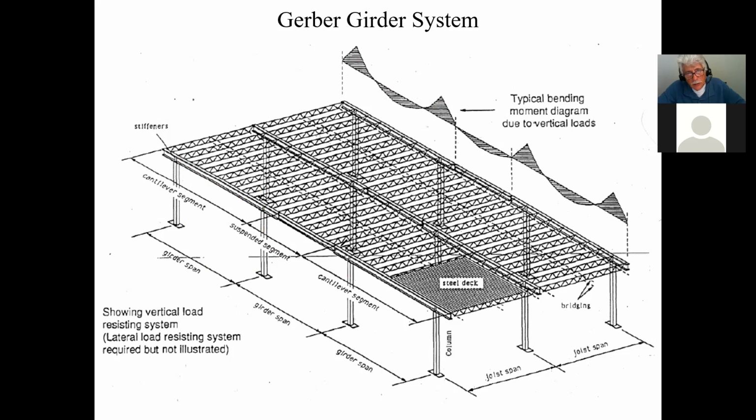Now you see here, this is the beam that gets suspended. Even for this beam here, instead of it spanning from there to there, the span would only be from there to there, and therefore even this would end up being a smaller beam. So these drop-in or link beams end up being smaller than you actually need. So there's a benefit at the end of the day of using this system.